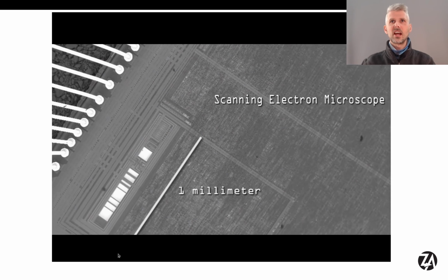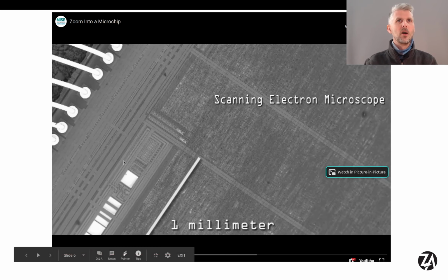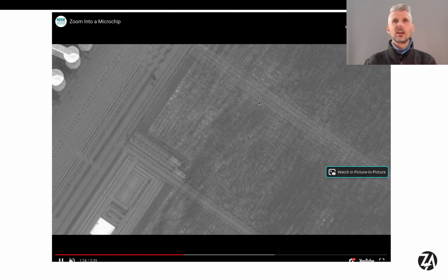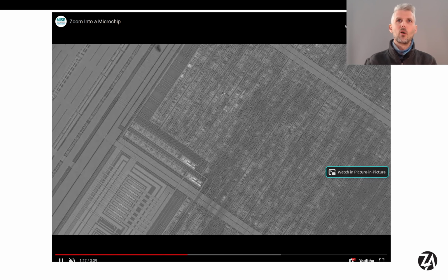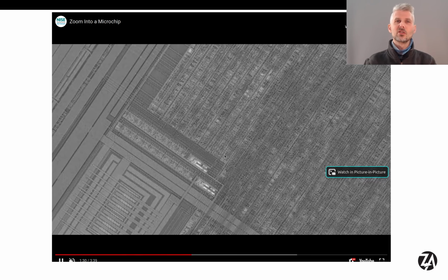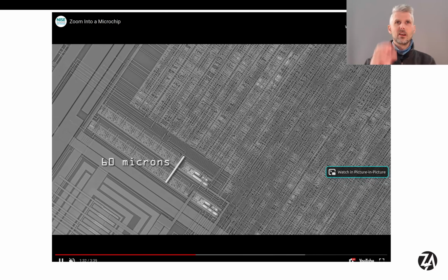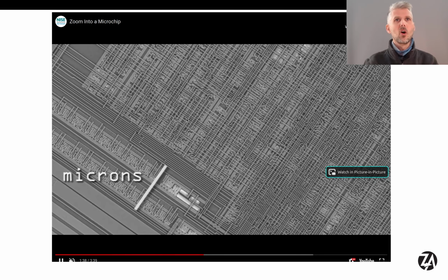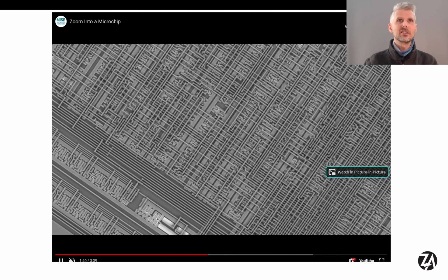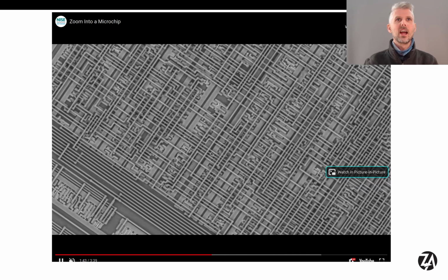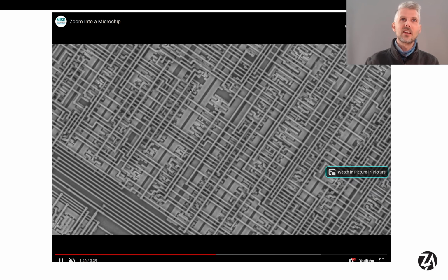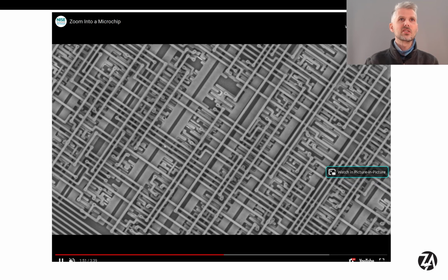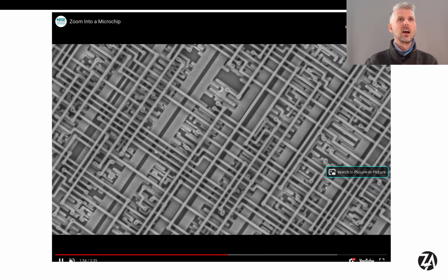And now we switch to the scanning electron microscope view. We've got these big power buses stretching out across the chip. As we zoom in, you see another set of parallel lines. These are the standard cells, the repeated small building blocks like AND gates and OR gates that are joined together. On the top you can see how they're all interconnected with these metal wires. And then underneath that we actually see the standard cells, with the top and the bottom being power and ground, and then the transistors, the MOSFETs that make all this work underneath that.